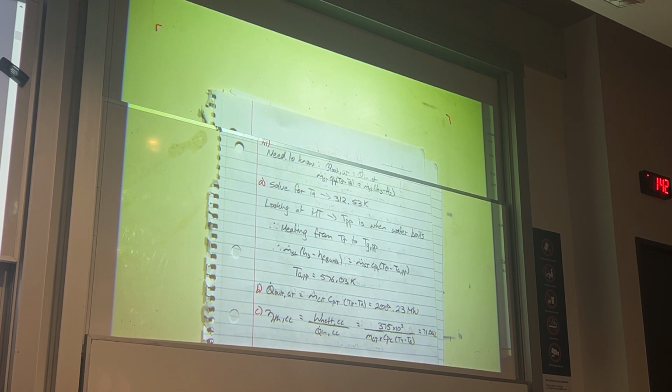And we know that because it's a giveaway through this flat line here. So here we're a saturated liquid, and here we're a saturated vapor, and you can see that corresponds to our pinch point temp. So the pinch point occurs when our water begins to boil, and then the amount of heat we can transfer is the difference between this temp and this temp, and this temp and this temp. So this remaining bit here down to T9, and this remaining bit here down to T2, that's not included in our energy balance for that part of the question.